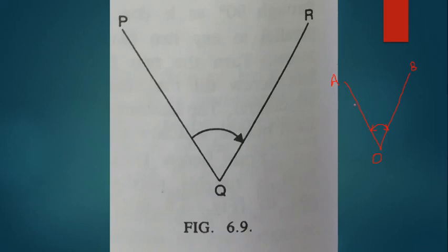Now I need to measure the angle between A and B. With 0 on my survey line OA, now I should operate the upper clamp screw. When I release the upper clamp screw and turn the telescope to bisect the ranging rod at B, that is, now the telescope is in line with OB. At first, you can approximately bisect the ranging rod with the clamp alone. When you operate the clamp alone, exact bisection may not happen. If it does happen, it will take a lot more time.